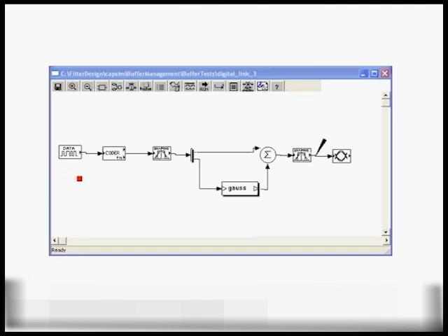So a source block is visited, generates samples, then all the other blocks are visited continuously until all the samples are consumed and a deadlock is reached, in which case the source block is visited again, it generates data, and again all the data is processed. You have a case where there is no more activity on the buffer, and then the source block is visited again, and another chunk of data is generated.